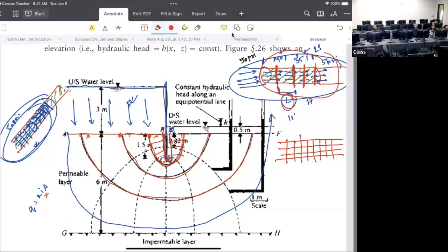Then in this one, this is our head difference and this is the length. Sorry. In between these two, whatever these two numbers are, our head difference, and then we know the length, we should be able to find the I. If we get this I and make sure this is square, it means this is scalable, right? It's equal everywhere. We are just trying to take a sample, but that sample is a representative sample. So how can we make it a representative sample? If we have the conditions in a way that the sample is equal everywhere, distributed all over the place, then it should work.